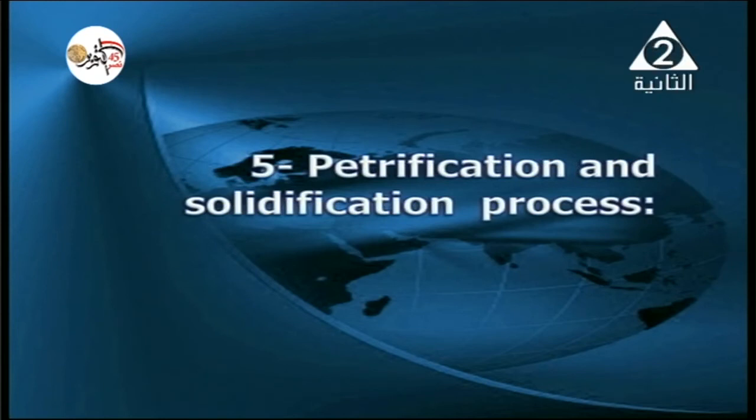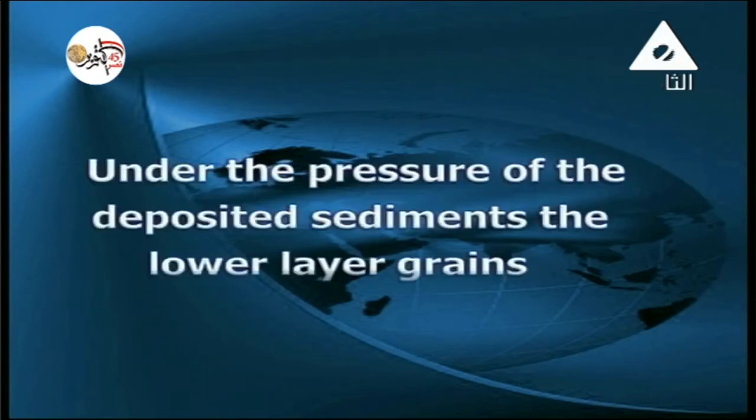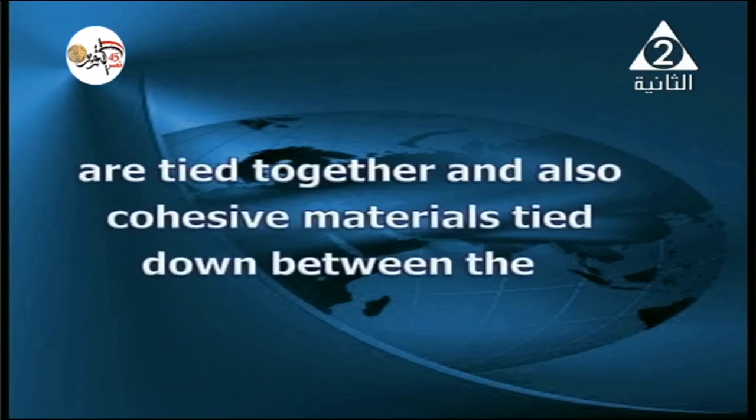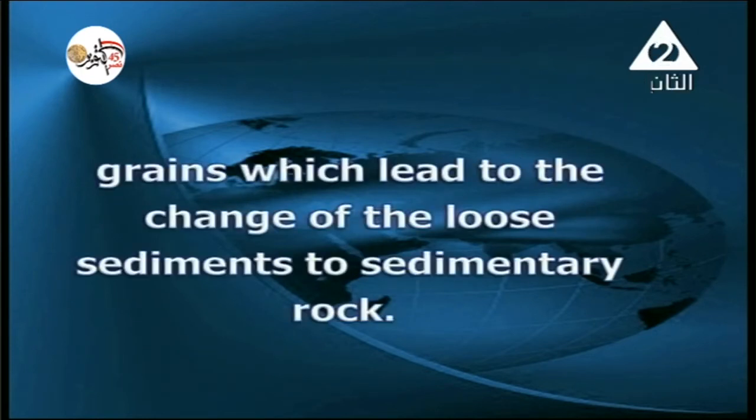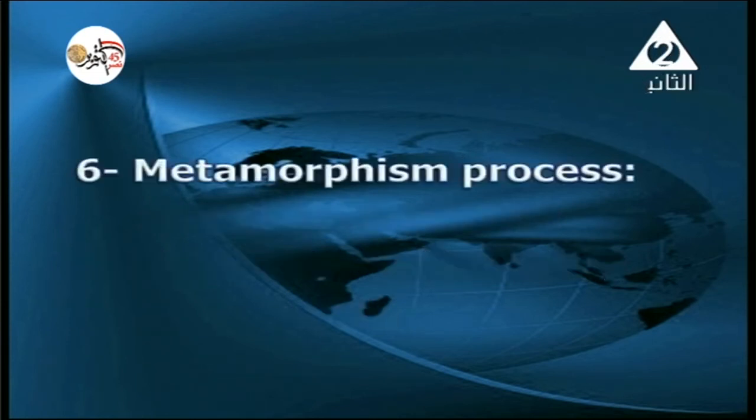Petrification and solidification process. This is a very important process in rock formation. Under the pressure of the deposited sediments, the lower layers are compacted and tied together, and cohesive materials are tied down between the grains, which leads to the change of the loose sediments to sedimentary rocks. Also, we have metamorphism processes.